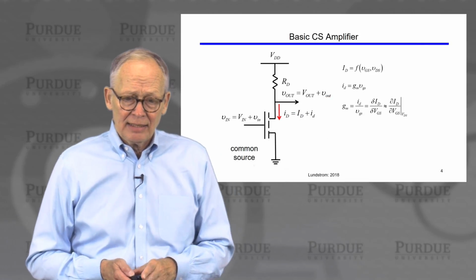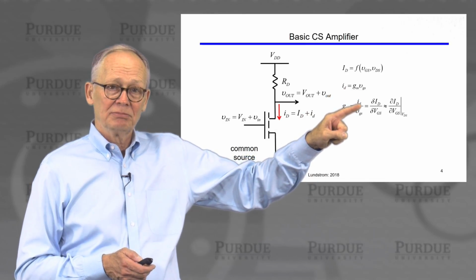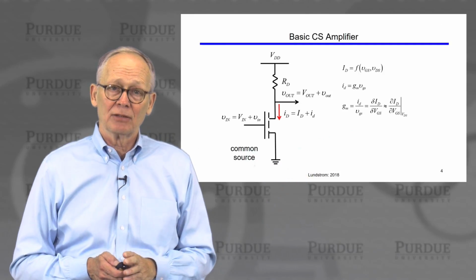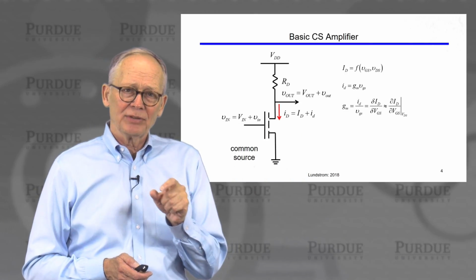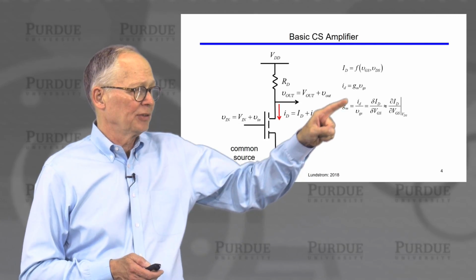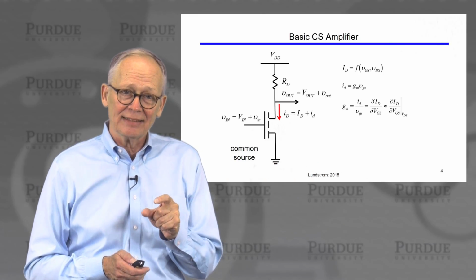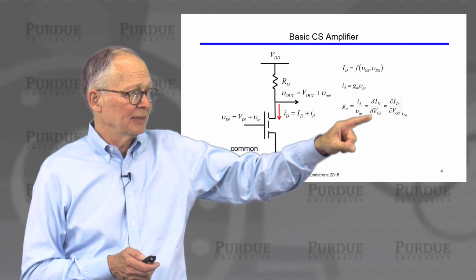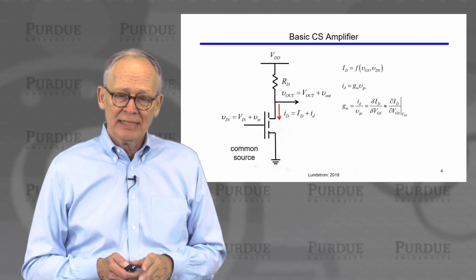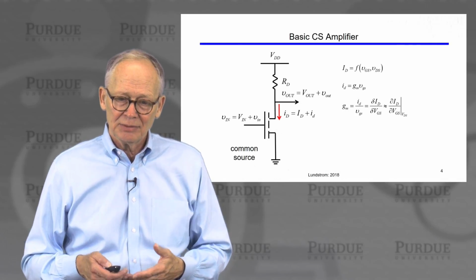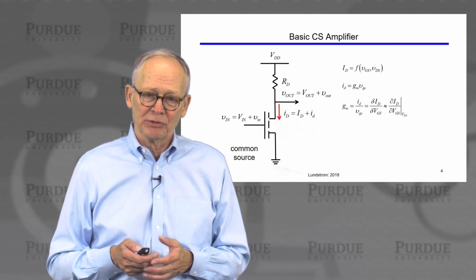All right. Now, what is that transconductance? Well, we just solved that equation. That's the small signal current in the drain divided by the small signal voltage we apply at the gate terminal. Well, that small signal is like a small delta in the DC current: a small delta I_D divided by a small change in the input DC voltage between the gate and the source. So if that increment is small enough, then that's just the derivative. The derivative of the DC drain current with respect to the DC gate to source voltage at a fixed voltage between the drain and the source.